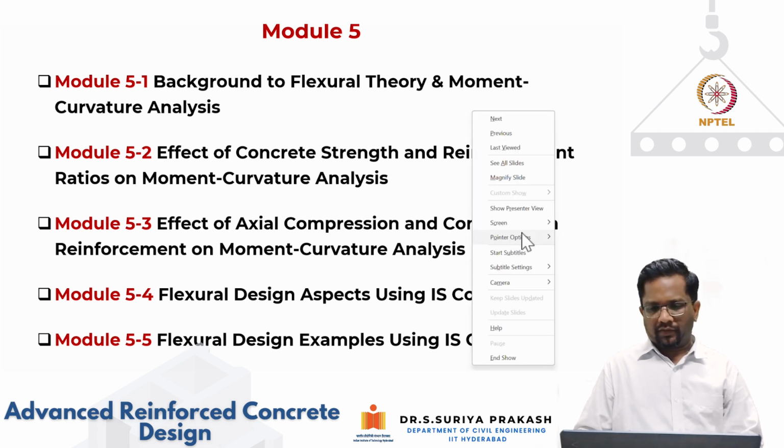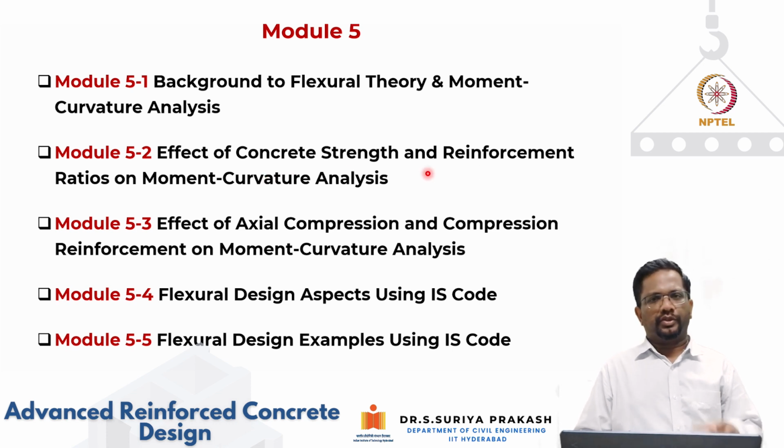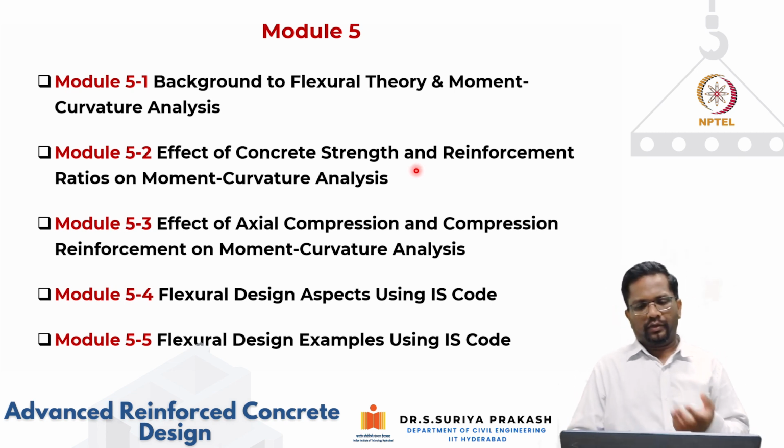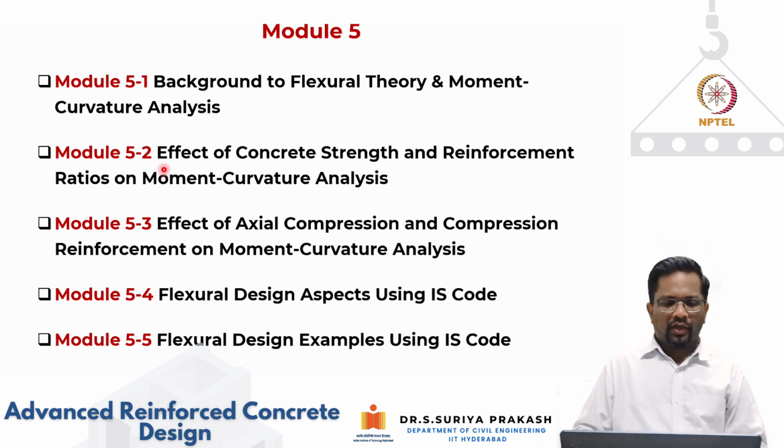The first one, we are going to talk about the background to the flexural theory and how we can do moment curvature analysis. In part 2 of module 5, we are going to discuss the effect of concrete strength and reinforcement ratios. What is the meaning of reinforcement ratio? If I start putting more or less steel in the concrete section, how the moment curvature analysis is going to change. That is what we're going to look at in part 2 of this module.